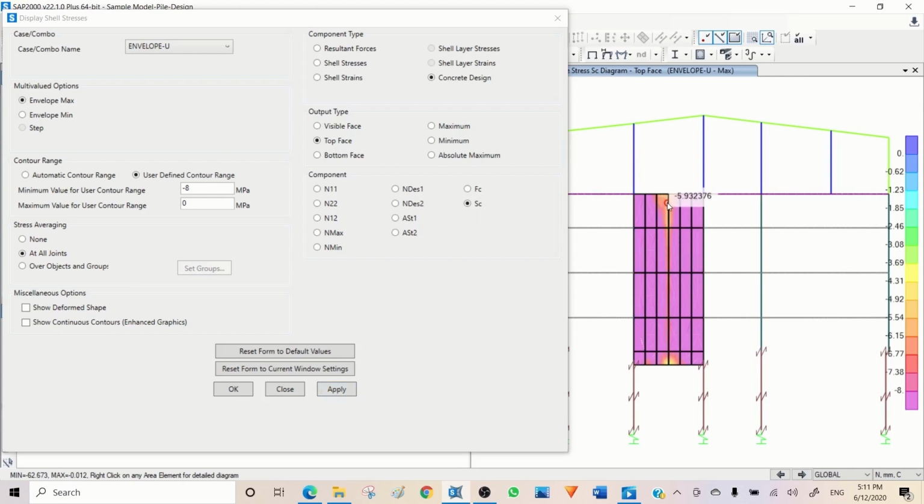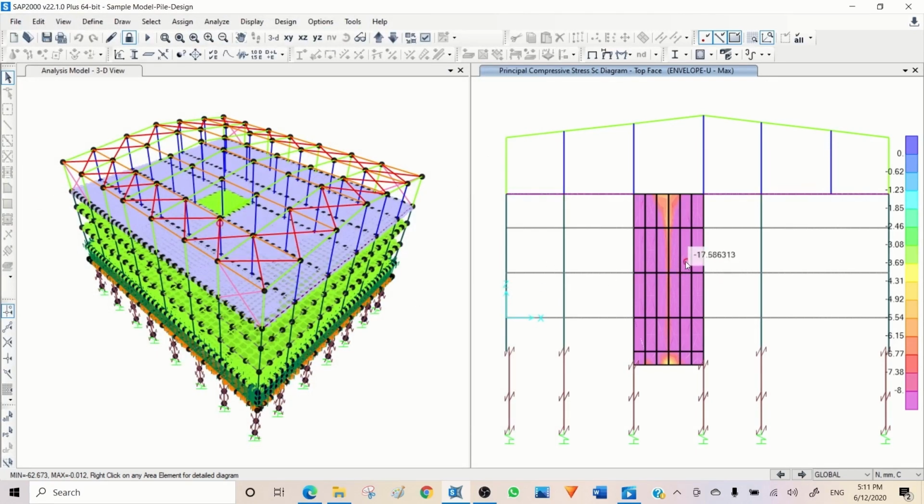So here it is less than 8, but here it comes to 15, 17, 25, which is not very normal for the whole thickness of the wall for such a small building. Even for a 12 or 15 story building, you wouldn't have such a big stress at this level. It depends, of course, on the arrangement, but that's not very normal. So this is for stress.